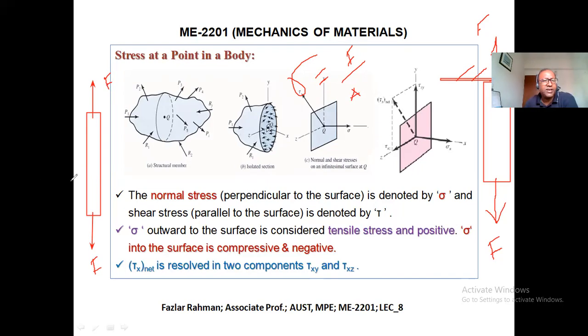You see, if I cut right over here, then I can make a free body of the bottom one. So this is the force working downward. So the force in the upward direction will be the same force, right? Still, there is no shear force working in this structure or bar. But if I cut the object in different positions, I can draw the shear force.